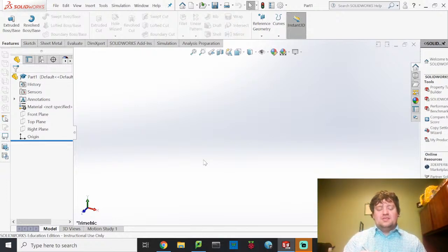They're made similarly to this. Now, if you understand the manufacturing process of a carriage bolt, there is a weld involved here. This is actually 2 different components. This is a slender rod, and this is the head of the carriage bolt. So this is manufactured as a 2-part process.